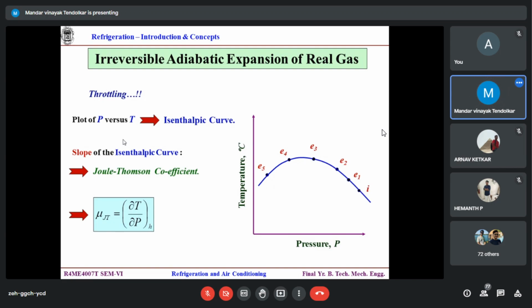Compressor, that is for the compression of the refrigerant, and then condenser, where the heat is getting rejected, and then this comes. We call it throttling, isenthalpic expansion, so that it offers the lowest possible pressure and lowest possible temperature, and then it enters the evaporator and absorbs the heat. This is how the cycle gets completed.